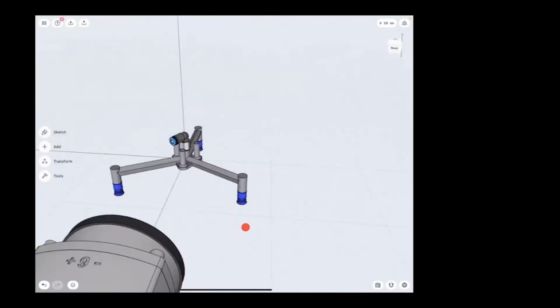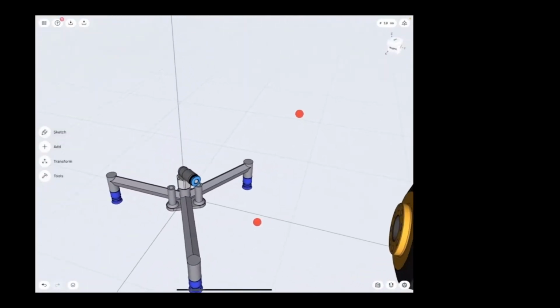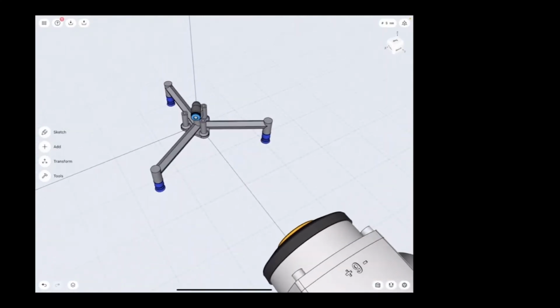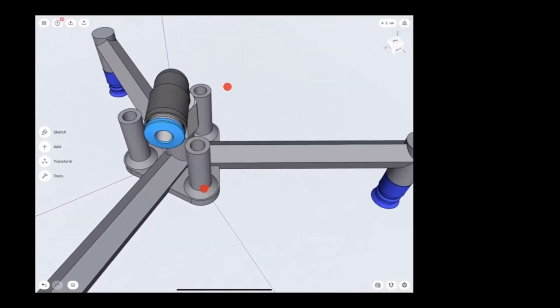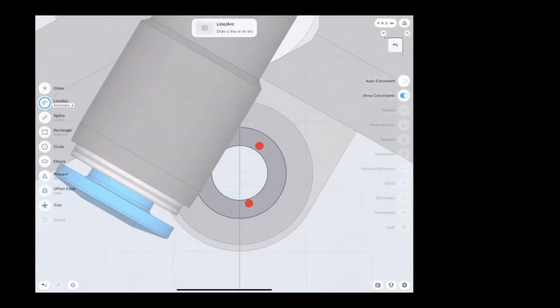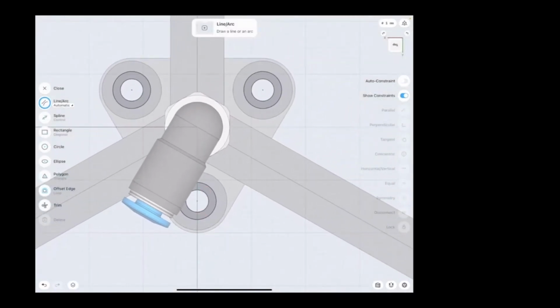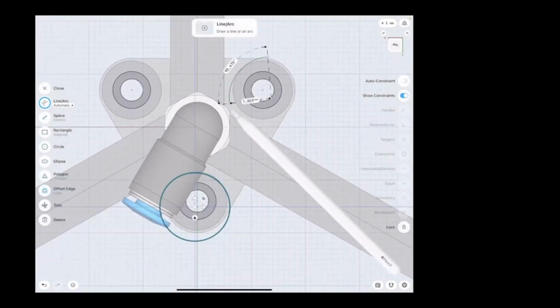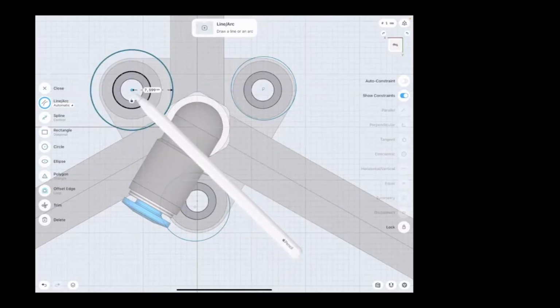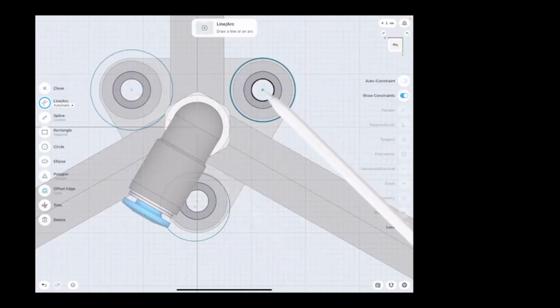There I have the printed part and the reference parts. Now I have to connect them to the robotic arm. I will design a bracket in the next few steps that will be placed on the top surface of the screw dome. The main shapes that define this bracket will be 3 circles placed on the exact midpoint of the screw domes.